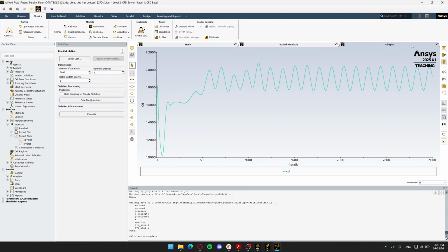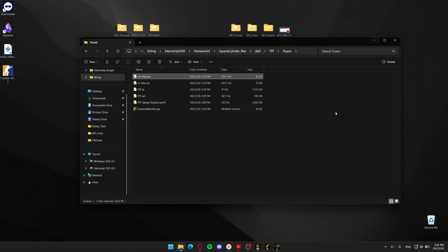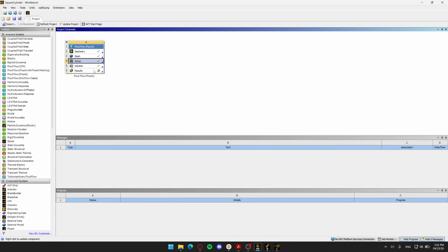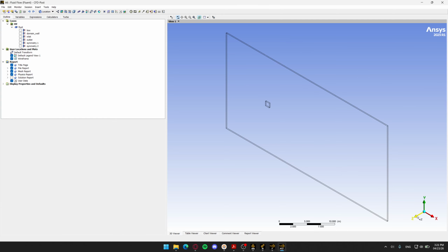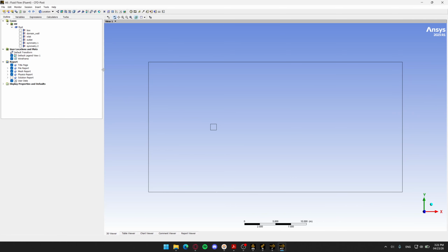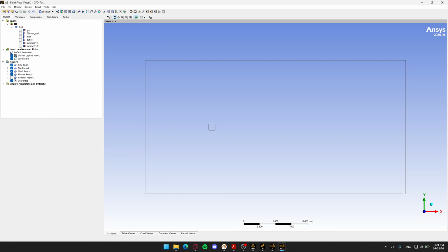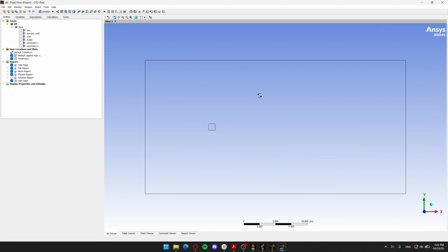Okay, and how to do a contour? Fluent is also pretty good, but you can do it in CFD-Post. Minimize it and click on the workbench again and click on the results. It opens like this. You change the plane to 2D and you get like this. So you click here, box, domain wall. It doesn't show anything, right? Yeah, it shows just symmetry because it's a surface.